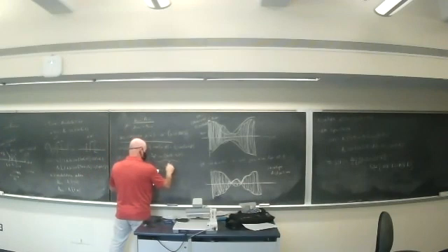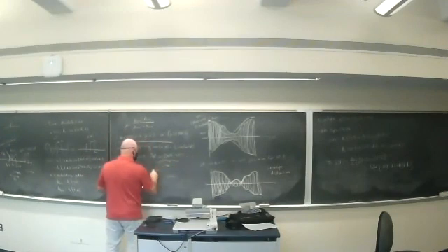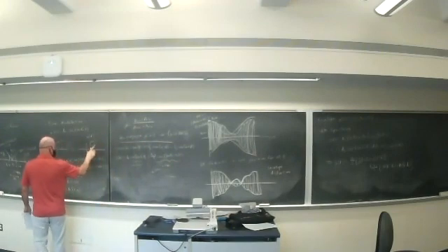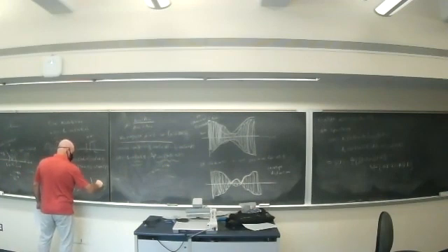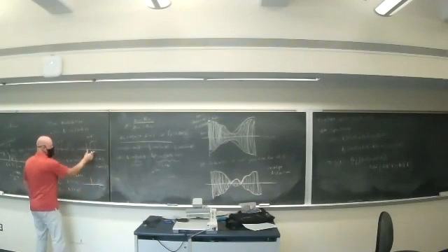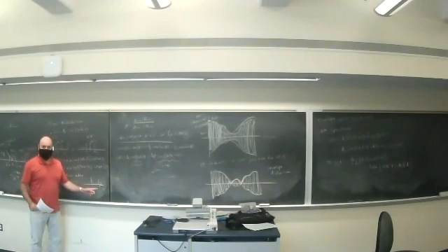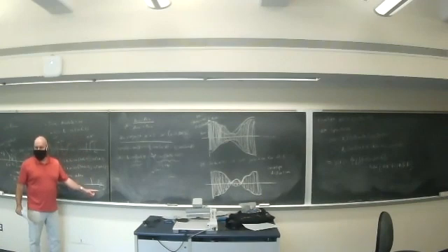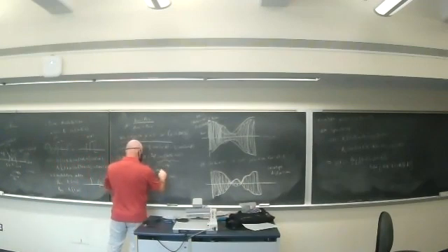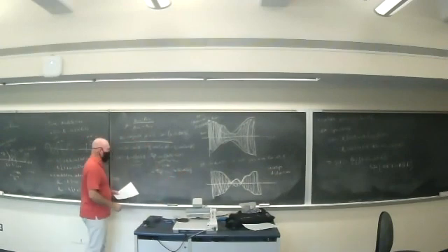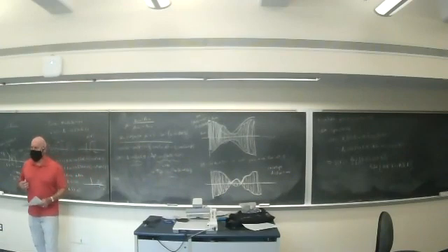This is actually the lower sideband term. There's another term that appears here. So now what my AM radio waveform would look like is at FC, I've got these two impulses due to this pair that get modulated up, and then I get the other impulse due to my carrier. Okay, so now I have plus AC mu over 2 cosine of the sum of the two frequencies. But I know how to calculate the power of a cosine signal.